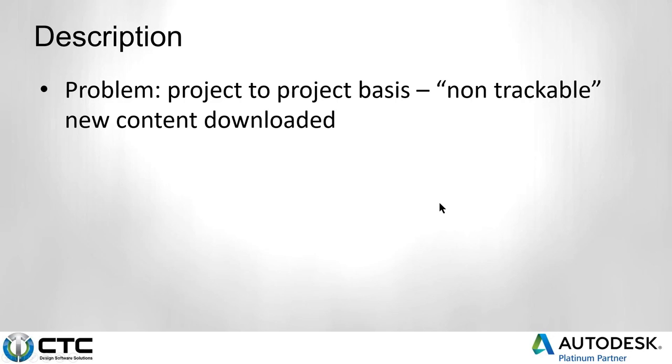So this is addressing the issue of, hey, the end user has downloaded an RFA file from BIM object or Daikin or a manufacturer, and it's addressing the parameters within that downloaded family and making it trackable through Spreadsheet Link, essentially, when you're exporting or importing the specific parameters associated with a schedule.